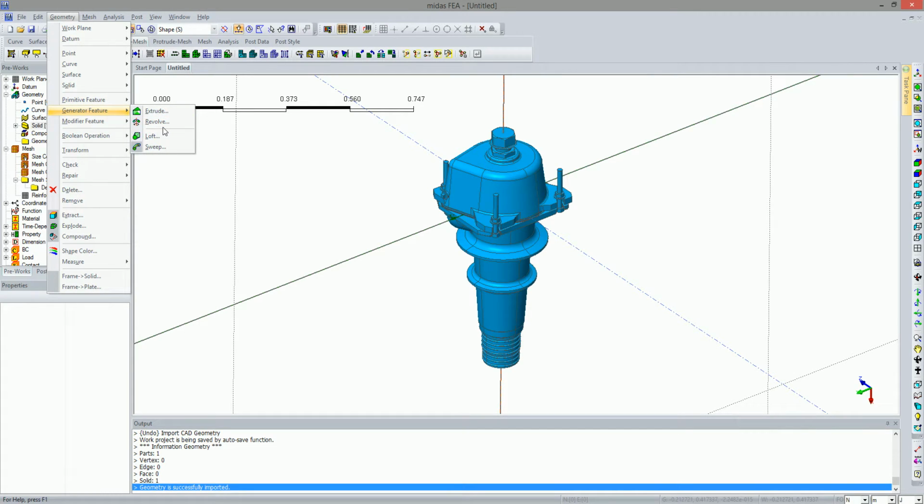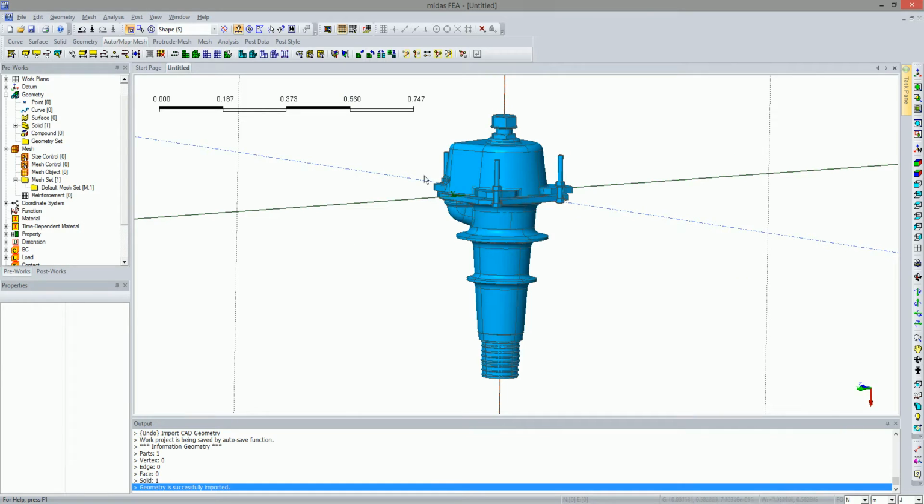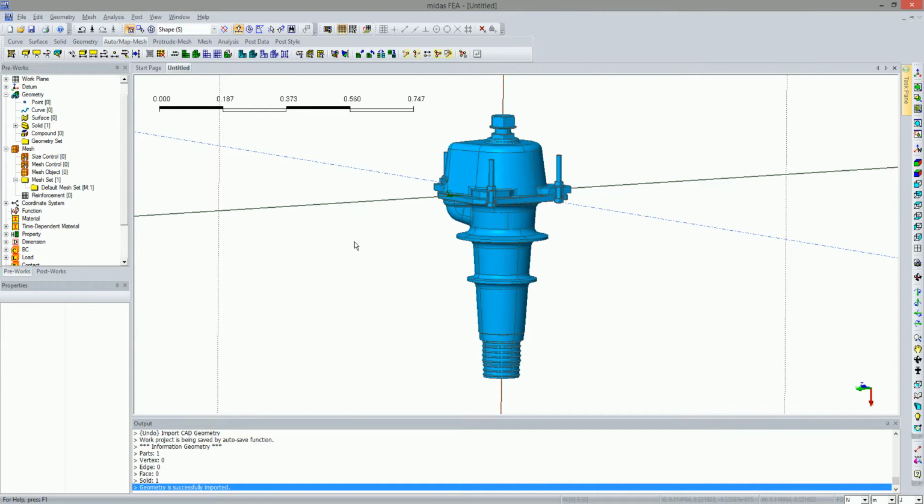Also, having surfaces or lines, we can also generate directly some sections. And for example, parts that will be connected to this, we can generate directly. We can remove faces, edges of these sections, so we can edit this and simplify it to wherever is needed in our model.